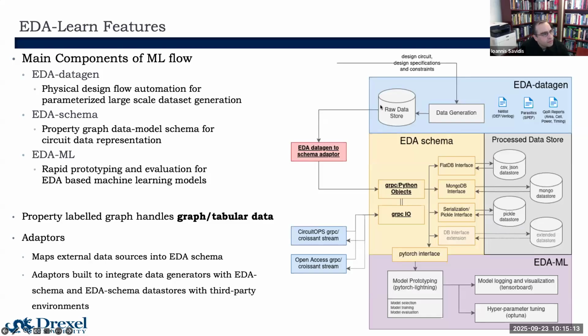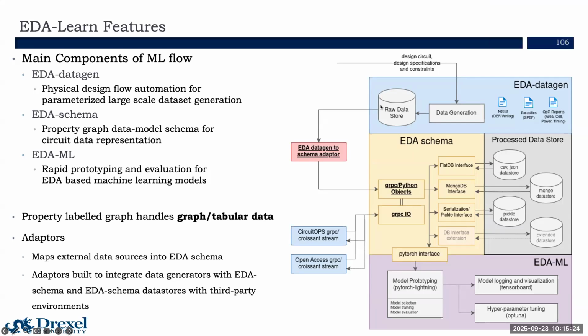Hyungjin? Yep, can you hear me? Thank you for the great seminar. I have two questions about grouping transistors from a netlist, such as the current mirror you showed earlier in this seminar. How much training data is required for training the networks? And the second question is, how do you label all those training data? It's not related to circuit performance, so I guess the circuit simulator cannot label them automatically.